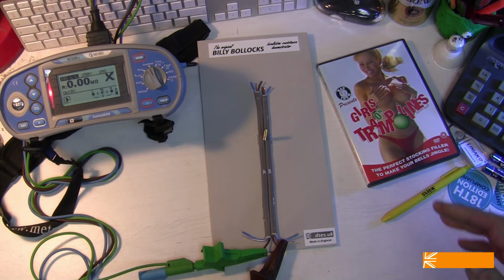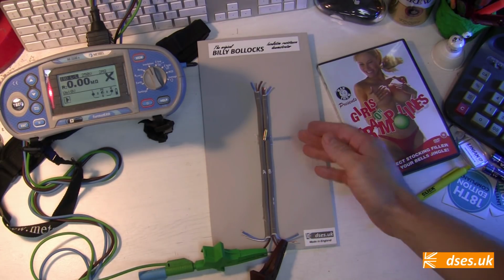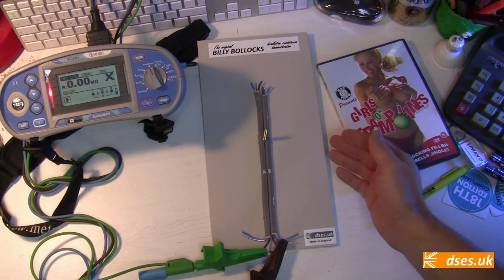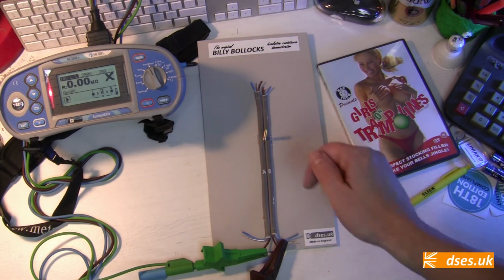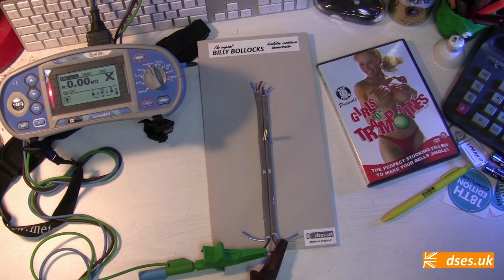What's happening here is that when the 250 volt goes up this brown wire, it has enough welly behind it to be able to jump the small air gap between the copper core and the screw where the plastic insulation is missing. It also has enough welly to jump the air gap from the screw into the second cable, as it too is missing its plastic insulation. It then travels back down this brown wire and into the tester, which reports the failure. Although it's open circuit on a dead test, it effectively goes short circuit when powered. If cable A goes to our lights, then we'd be seeing them illuminate whenever cable B is powered, as we have a leak between these two circuits.